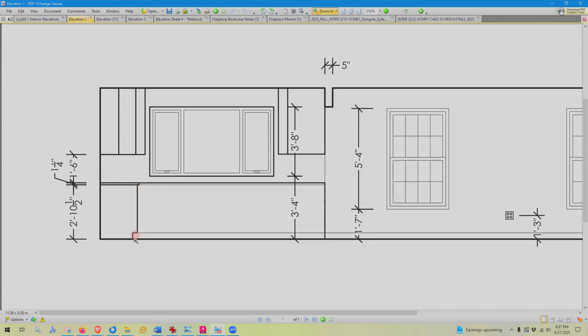Well, I'll call it a medium line. And these millwork cabinets that are up here, those are going to be medium line as well. So generally speaking, those lines are the next heaviest. And I will often, and it looks like I wasn't consistent here, but I will often make the perimeter around a window a little bit heavier. And then all of the nuts and bolts of the window, inside the handles and the mullions and all of that stuff, I'll put that on a very light line.